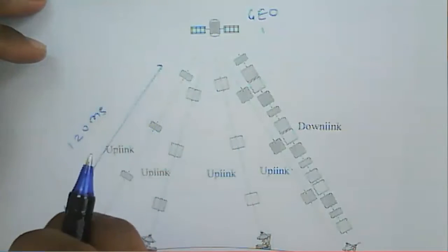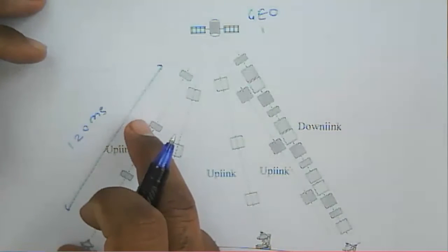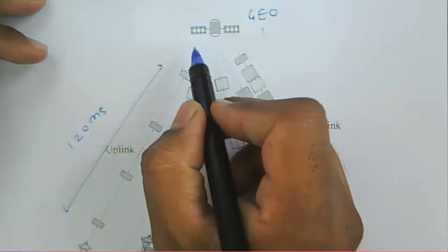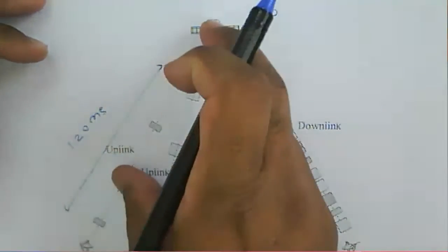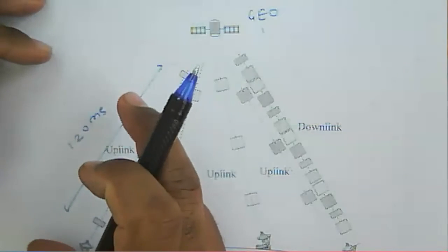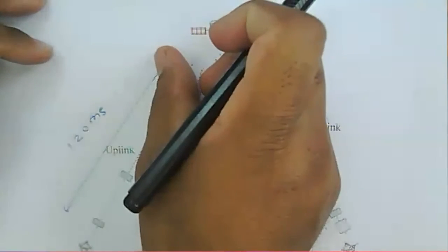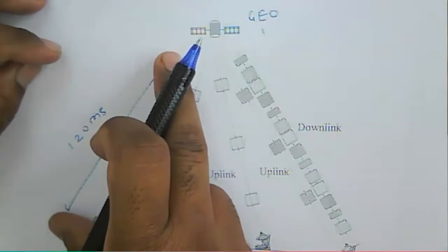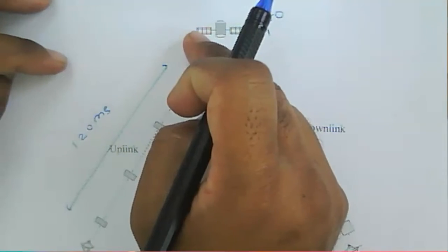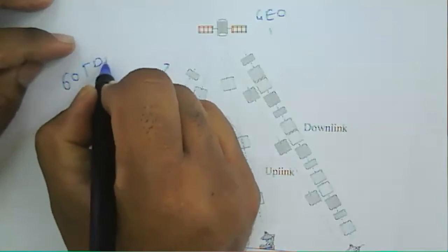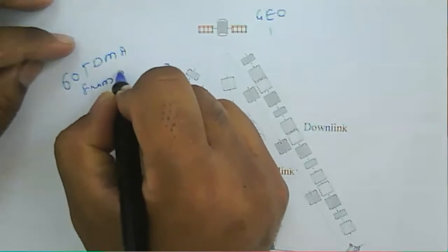That is nothing but the Earth station transmitting a data burst, which then arrives at this particular satellite with a delay of 120 milliseconds. So the arrival time at this satellite is about 120 milliseconds, approximately 60 TDMA frames of 2 milliseconds each.